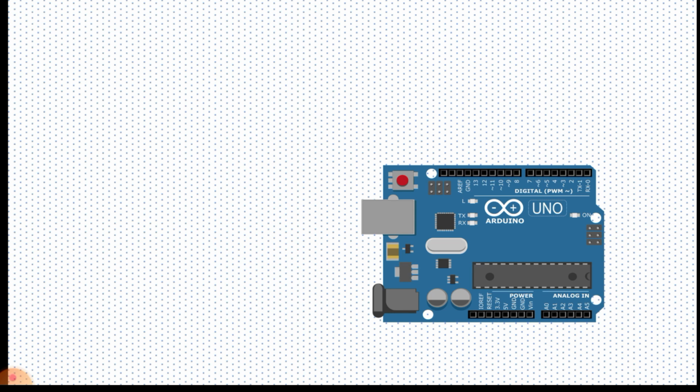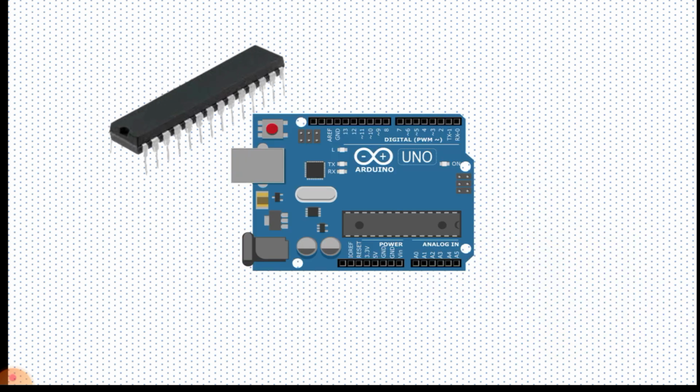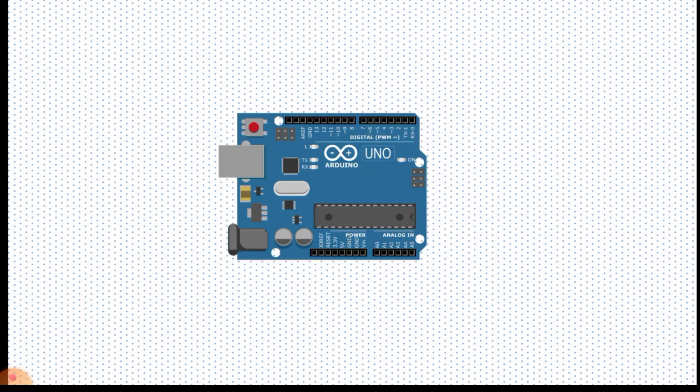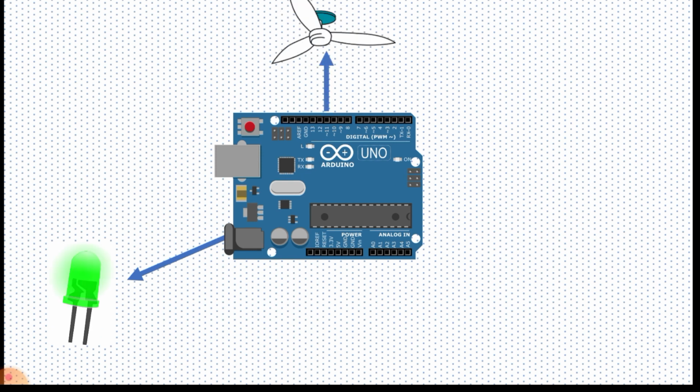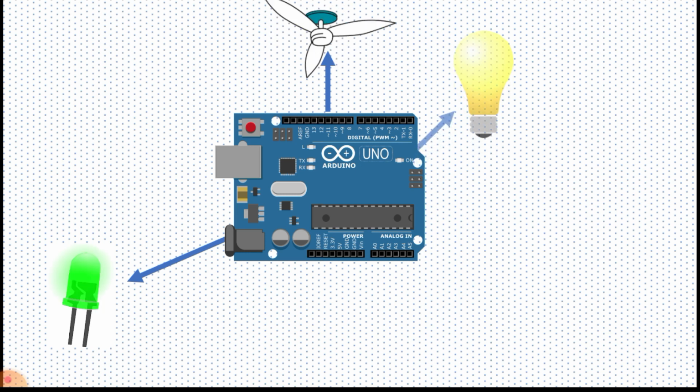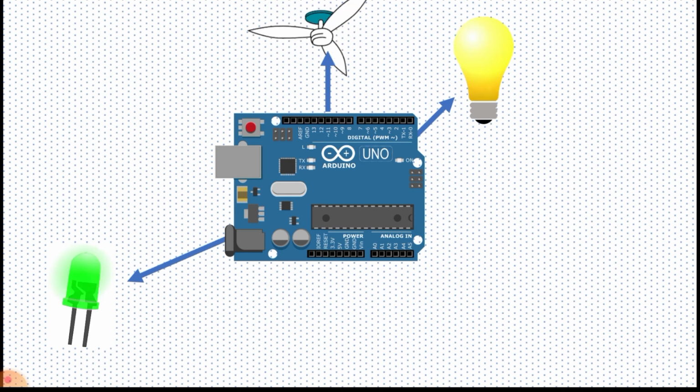Okay, let's go. This part is the microcontroller, model ATmega328P. Let's see what kind of projects can be done using this development board. You can set a time for the LED bulb to turn on or off. You can also turn the fan on or off for a specific time period. You can set a time duration for an electric fan. You can control the AC bulb with this relay. You can set the light to turn on or off automatically based on the temperature level.